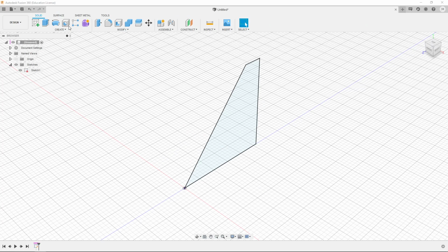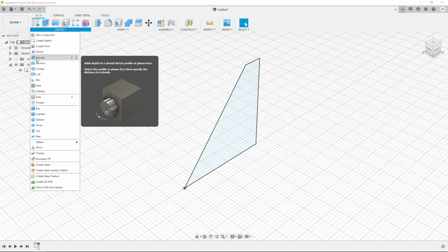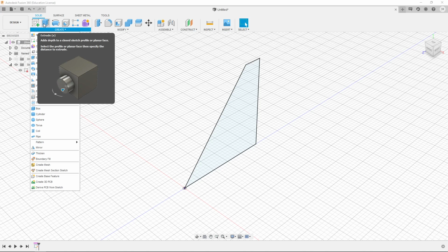Since we're not in a sketch, our menu is back to the original. In the Create section, the first 3-dimensional tool we have is called Extrusion, or Extruding. E is also a shortcut on the keyboard. We can press the Extrude button, or it's also the second button in my menu right here. And it gives us an example. It says you can take a 2D profile or sketch or face of a 3D object and pull it out or cut it in to the third dimension.